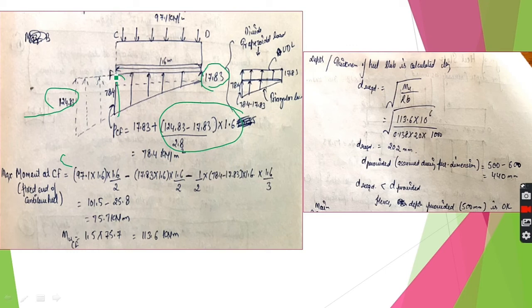Now when we do a trapezoidal load, we divide this load into 2 diagrams, that is one rectangular load and one triangular load. So if this is your trapezoidal load, if this value is 17, then this will also be 17, and this will be here total value 78, so this will be 78 minus 17. So now we have two types of loads here.